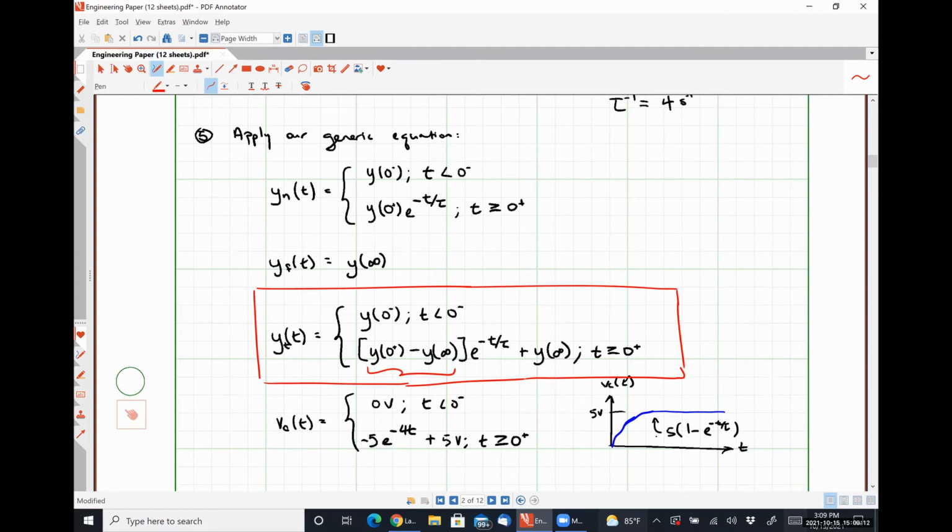No. This differs from yesterday because now everything isn't 0 at t equal to infinity. Things will have finite values at infinity, and that could not happen on Wednesday because we were taking sources out. Now we're putting sources in, so we're forcing quantities to have DC values after a lot of time has elapsed. Okay, it's a small distinction, but it's a very, very important distinction.